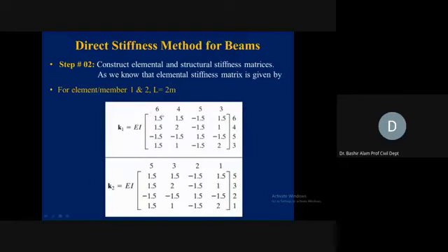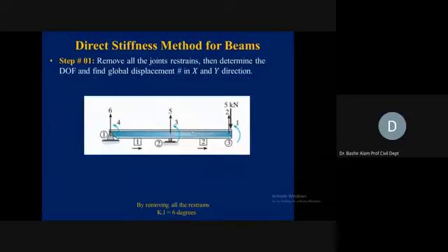So as I said, it should be 4, 6, 5, 3 for element 1, K1. You can see, and this should be the same order, 6, 4, 5, 3. If you want to confirm this, 6, 4, 5, 3. So here element 1, 6, 4, 5, 3. Again, I'm saying if you are using those element coefficient values, you cannot use 4, 6. Why? Because first translation was given. So translation, this vertical, will be coming first, followed by the rotation, 6, 4, 5, 3.